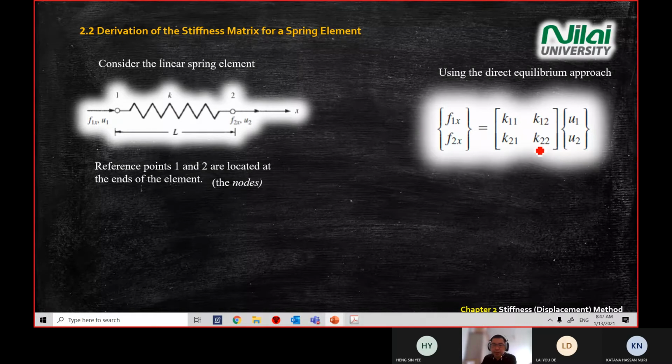So these are the coordinates where you should put your K correctly. This is the general equation that you should have. If you have a 2-point system, then you will see 2 forces on the left, 2 displacements on the right, and 4 unknown stiffness values inside the matrix in the middle. Are you able to see the logic why we put this equation together?